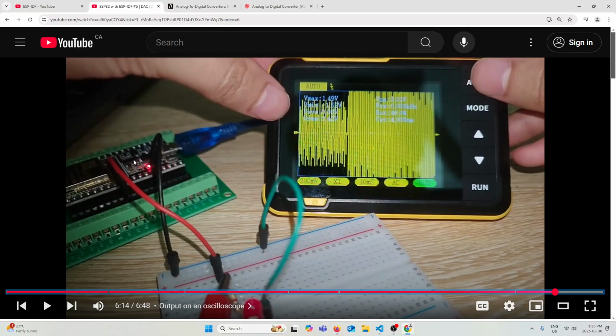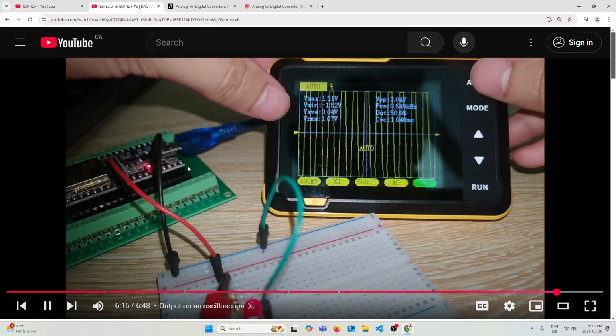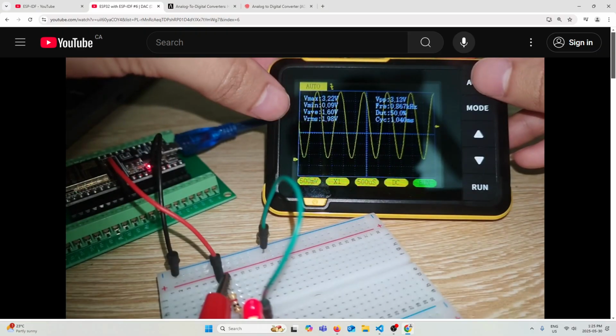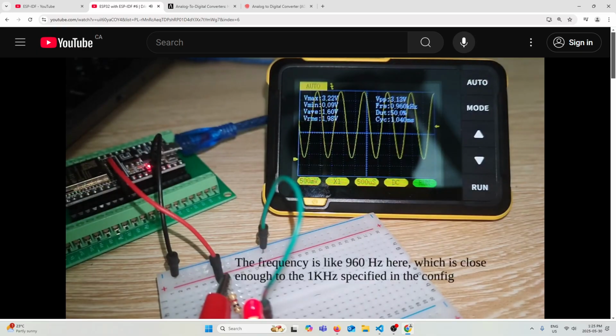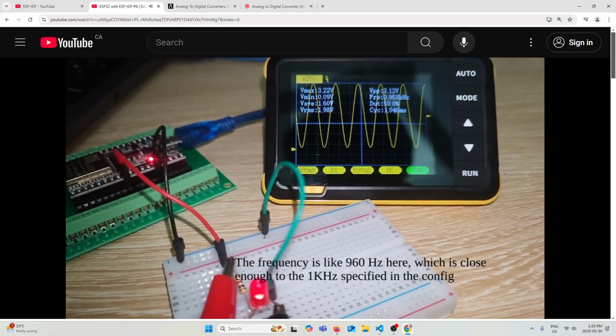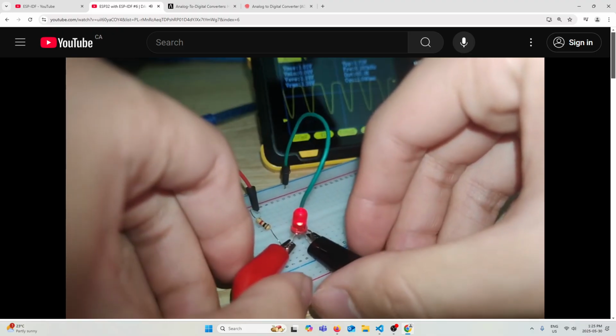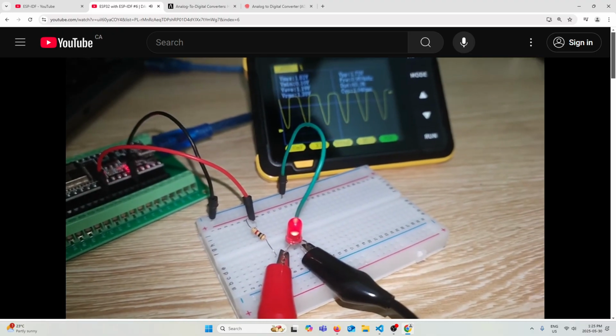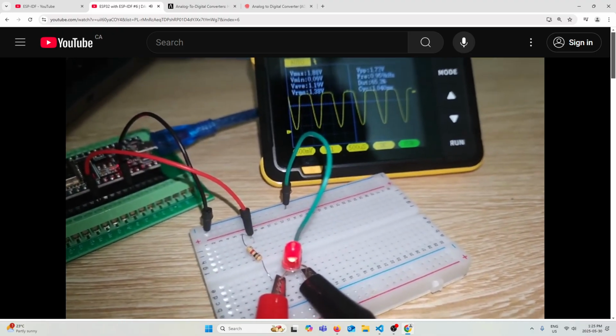I think this is literally the exact model he's using. I have it right here. Note that I use the probe on both the resistor and the LED. If you try to use it with the LED alone, the waveform will look distorted as you have to account for the voltage drop across the resistor.